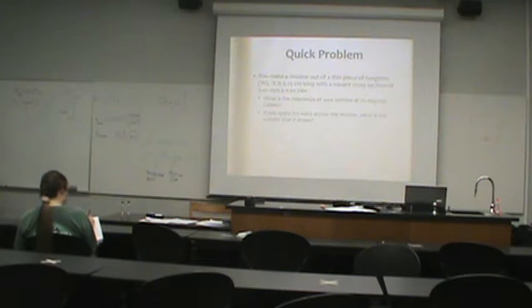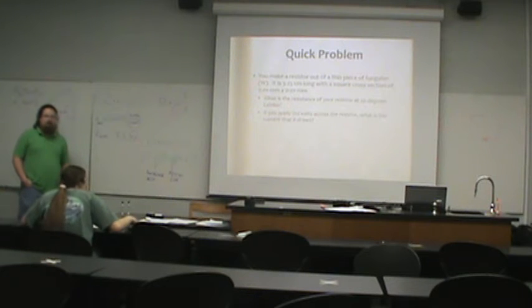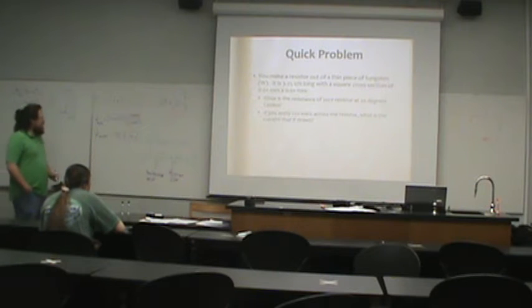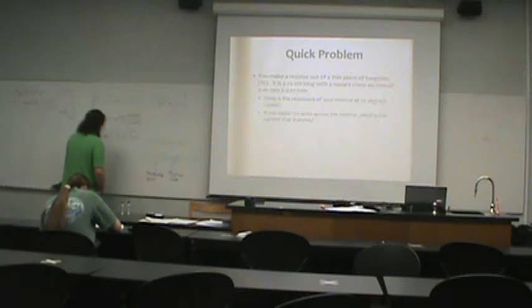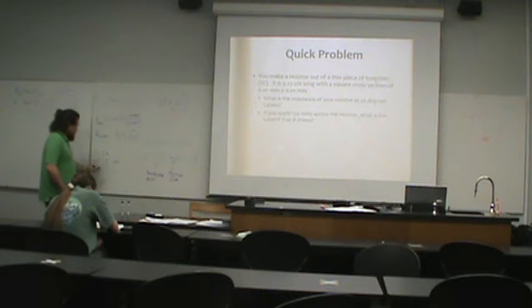If we were to take this particular resistor and plug it into a 120 volt battery, what then would be the amount of electrical current flowing through it? V equals IR. Correct. We can do V equals IR, plugging in 120 volts, solve for current, times 18.2, and we are going to get a number that, electrically speaking, is irresponsibly large. 6.59.